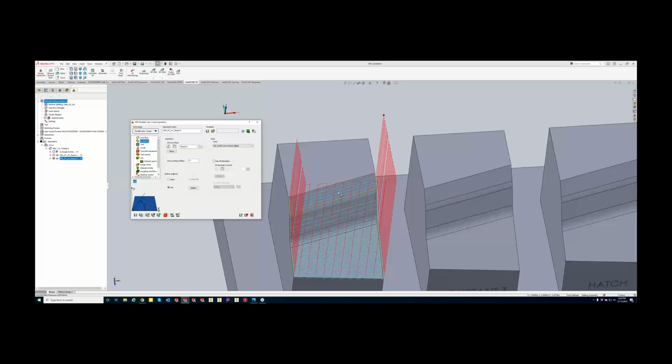Now, like we talked about last week, on these more vertical walls we're not going to get as nice of a finish versus this more flat area right here. But we'll go through and show the differences. So for drive surface offset, we can do defined by angle. For avoid surface edges, if we go right up to the edge, we should see our tool path bump up right towards the top now. So that tool is going to come right on the exact edge.